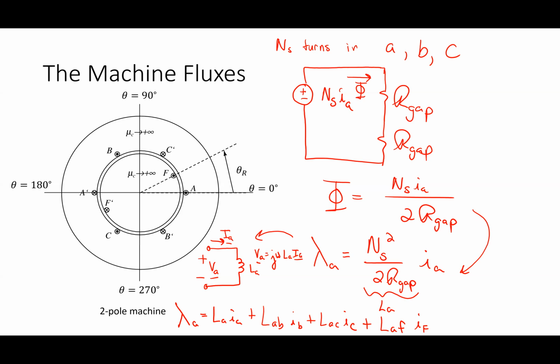In other words, I take the derivative. That's taking the derivative, isn't it? So what I did, I took the derivative in the phasor domain. If I take the d by dt in the time domain, that's the same as multiplying everything by j omega. You've seen that before with Fourier stuff, and you should be getting somewhat comfortable with that idea.